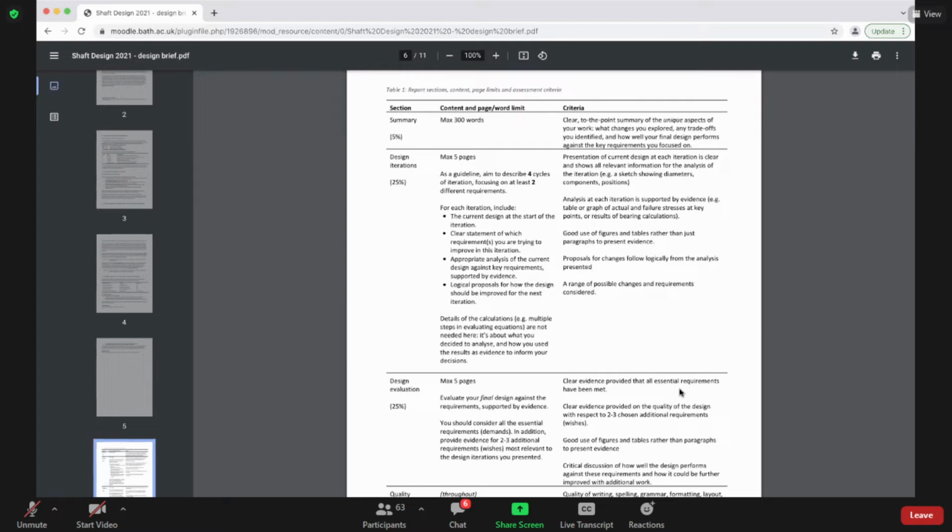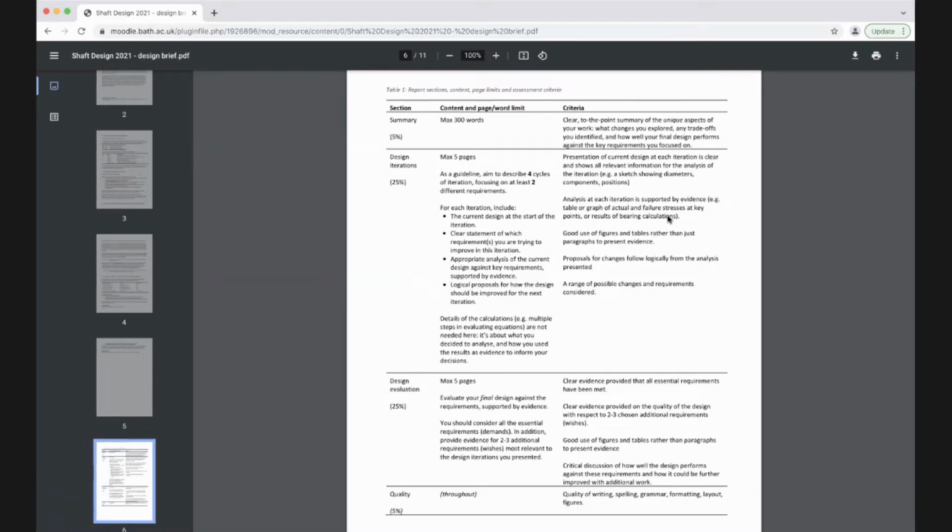Similar question about the keys, just checking that is coming out as a reasonable answer. Again, that will vary depending on what material properties you're assuming the key is. There was something about that on the forum if you want to look more about that. But yes, it's quite plausible that the lengths that you calculate for the key are fairly small. And that just means that the torques that the key is carrying are not that big. So even a very small amount of material would be enough to transmit them. And that is quite often the case. It's not always the case, which is why we have to check.